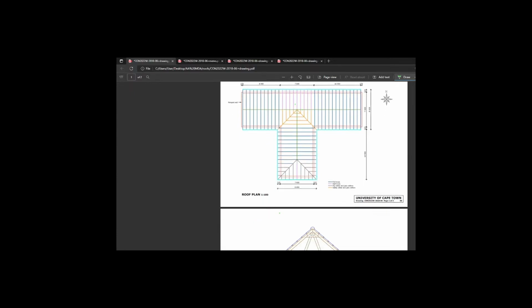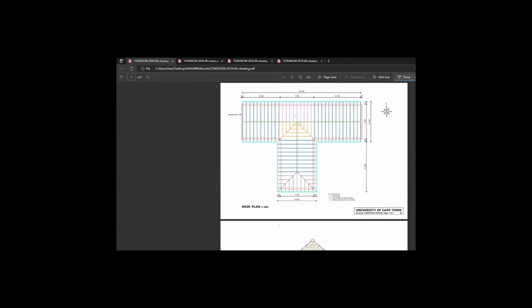Jack rafters. Okay, the jack rafters, thank goodness there's less maths involved here, really. This division by 5 works, and I think it works in every scenario, regardless of what this angle is. We have a 45-degree angle at the moment, and I think it might apply to all angles, but I'm not sure. This one is a 1/5 length of this. What would be easier is if I actually do it on this side, because you can see it better. So that is 1/5. I'm just going to put a multiplier of 5. Then it's 2/5, 3/5, 4/5. Okay. And this is 5/5.